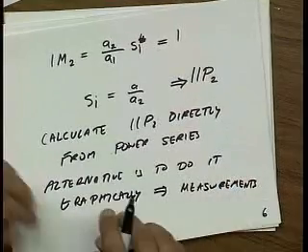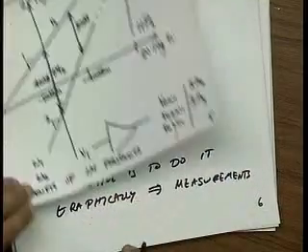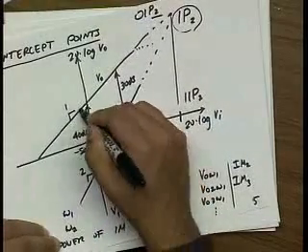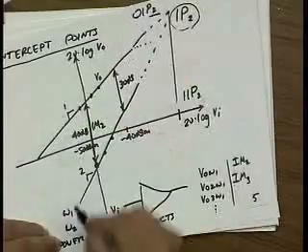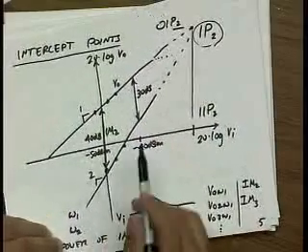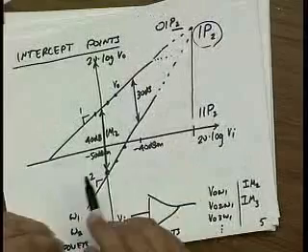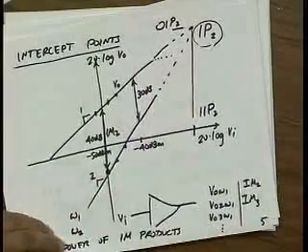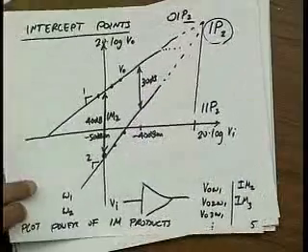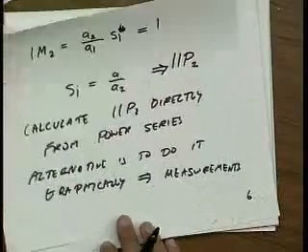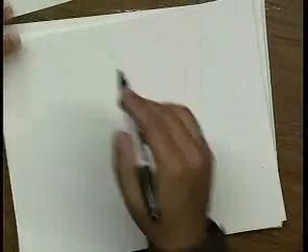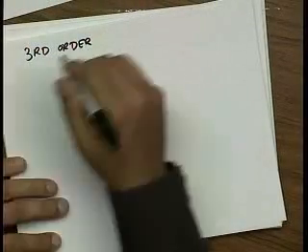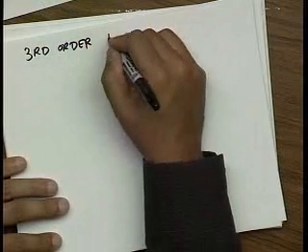We typically will measure the IM at several input points, basically verify that the amplifier actually fits within these lines. We do that just to make sure we're not crazy. You know, maybe the amplifier is hooked up incorrectly. Make sure the slope is right, and then you extrapolate to get your IP2 point. Okay? Well, a very similar concept is your third order IP point. And in fact, it's a more important concept for most systems.